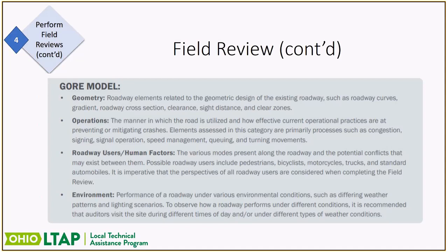You also should look at who's using your roadway and the human factors involved. Do you have a lot of pedestrians, bicyclists? Are there a lot of trucks on that roadway? Do you have a school close by? Children actually look at their environment in a much different perspective than adults do. So if you have kids that are walking back and forth to school, that's something to factor in the area that you're looking at. And then the actual environment itself.